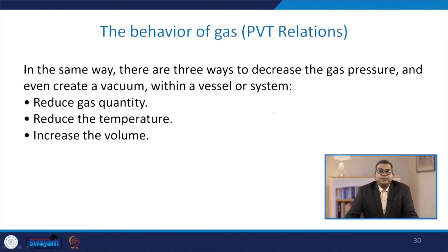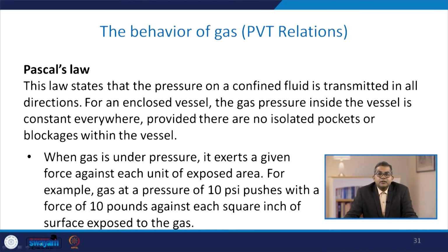In the same way, there are three ways to decrease the gas pressure and even create a vacuum within the vessel or system. One is to reduce the gas quantity, second is to reduce the temperature, and third is to increase the volume. Now, let us talk about Pascal's law.